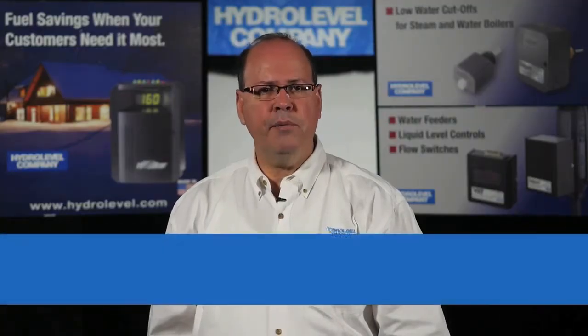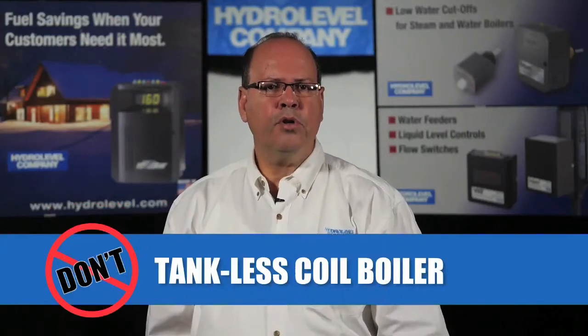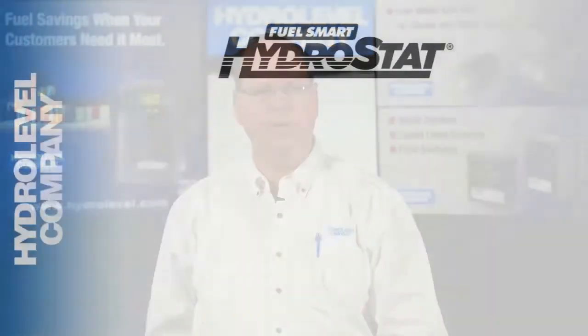The economy feature uses a proprietary algorithm called thermal targeting to conserve fuel by reducing boiler water temperature whenever possible, without sacrificing heating comfort. Do not use the economy mode if the boiler is equipped with a tankless coil. Thermal targeting can calculate temperatures that are too low for tankless coil operation. We'll cover more on thermal targeting later.